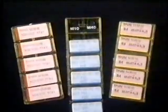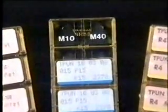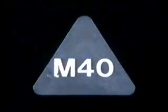Care should be taken to choose the right grade. That way you get better tool performance and better surface finish. To help guide the operator, each insert has a number. The higher the number, the tougher the tool. The lower the number, the harder the tool.